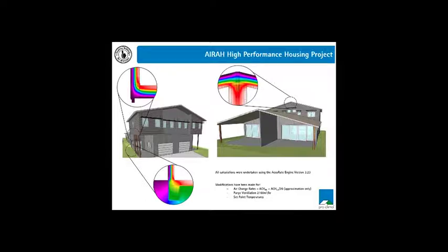This was a duplex in Wollongong, looked at all the key features that make up a well-designed building, including a highly insulated building envelope, thermal bridging, which you're looking at those circles. So the key areas where you might get excessive amounts of energy leakage out of your building, looking at an airtight building envelope, looking at high performance windows, and looking at ventilation systems to maintain indoor air quality and healthy conditions, as well as purge heat out of the building in summer.